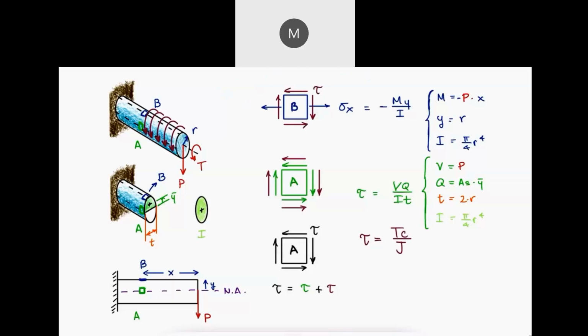And of course, we wouldn't compare them individually to a maximum allowable normal stress and a maximum allowable shearing stress respectively. What we know about a material in the real world is its material properties, such as the yield strength or the ultimate strength. For this reason, it's important to find the maximum values of the shearing stress and the normal stress at location B for when the stress element is rotated, and the angle of rotation for which that stress element yields the maximum values of stress.